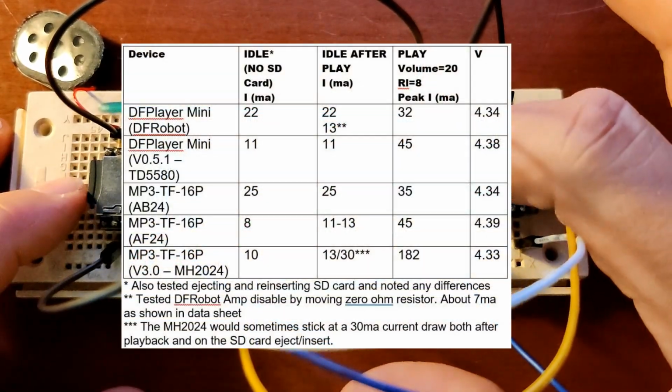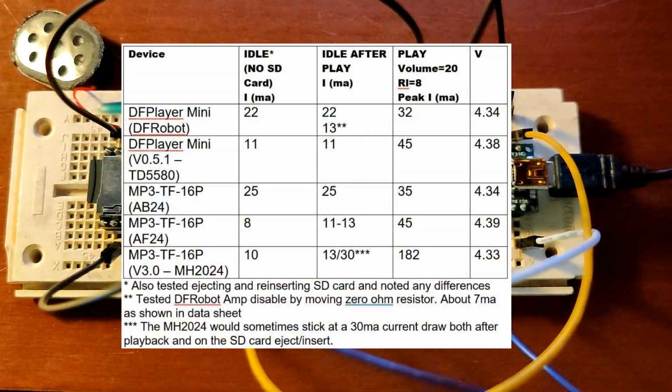I also decided to do some current measurements. I figured they would all be comparable. Not really. For the test I used the same soundtrack, volume set to 20, and an 8 ohm speaker load. The results were varied across the devices. The TD5580 and the JL AF24 chipset looked to be the best for battery power with an idle current draw of about 11 milliamps.